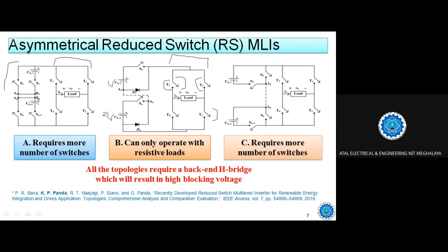Stress and standing voltage are almost equal. And the standing voltage, in terms of definition, is this: when any of the switches, let's suppose T1, T2, is not operating, at that time, how much stress is across this switch? That is called the standing voltage. You need to think of it, because when it is off, it may face a very large amount of voltage. So I will do a detailed analysis with one of the structures. We'll take one of the structures and think of how the stress analysis can be done.